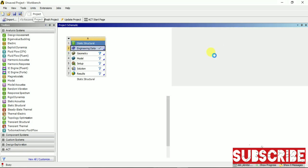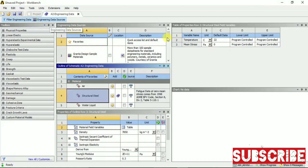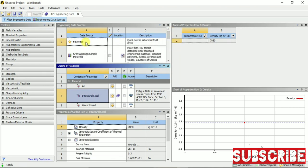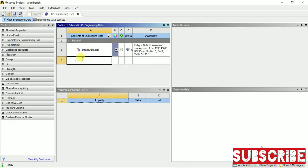Then here is the Engineering Data. Engineering Data is a warehouse of the values of the most common materials which a person can use. Go to Engineering Data Sources. From here you can see different types of materials that people use in their analysis, but it is not a constraint. If you want to use some new material, you can definitely use it by adding that material. You can click here and add a new material.